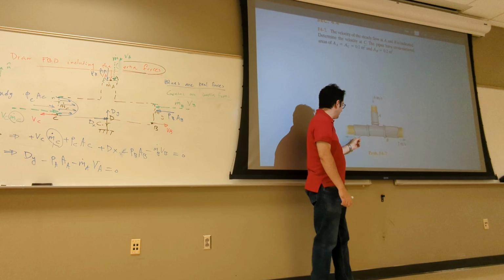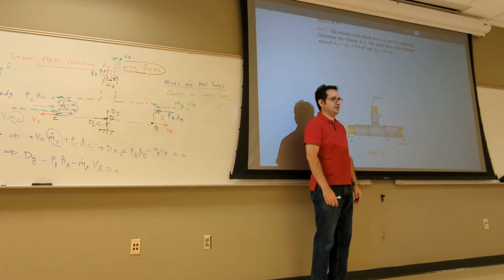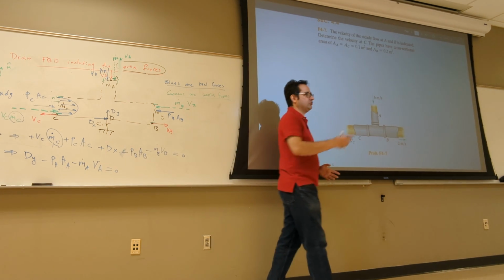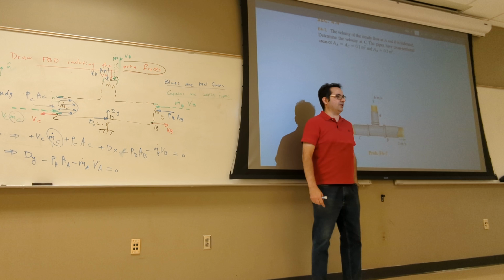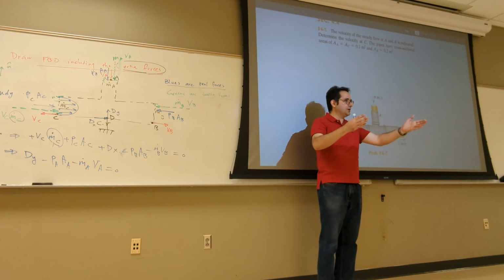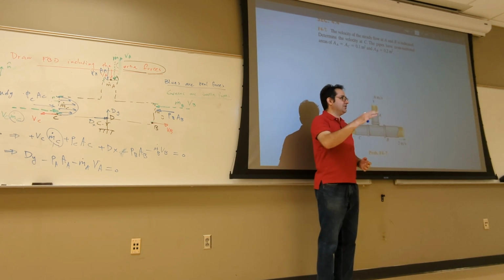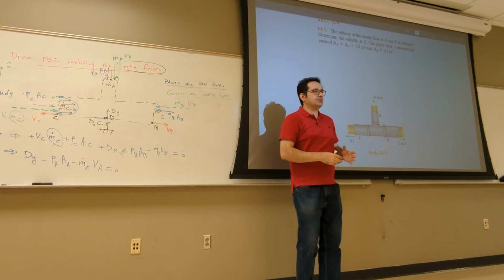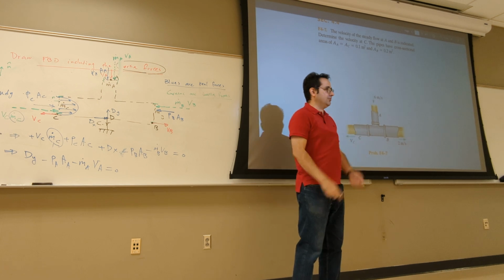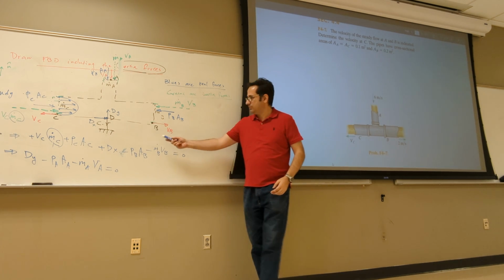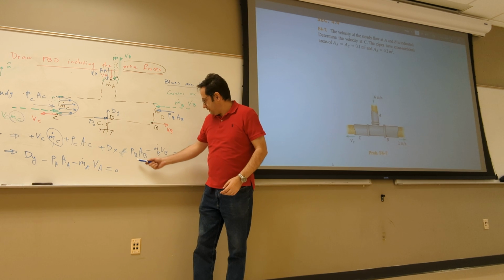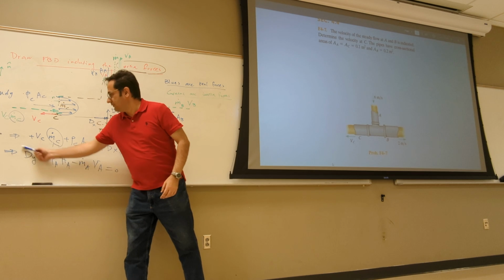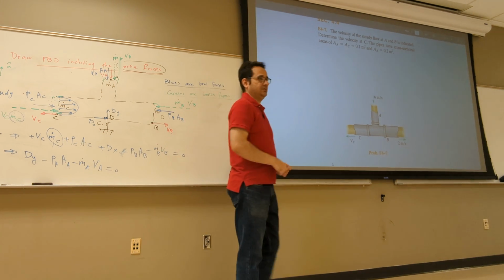In some cases, it may be equal to pressure at C. You see that? So it may not be very straight, but it's not too hard. It's just the same thing you studied so far. A combination of continuity, Bernoulli, and momentum. We haven't studied energy. So after we study energy, we'll give you a problem where you can combine these to find numerical values. So then you put it here, PA, there you go. You have the area, you find dy. That's it, one line.